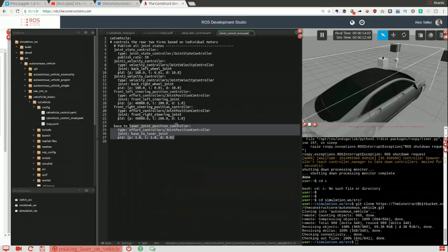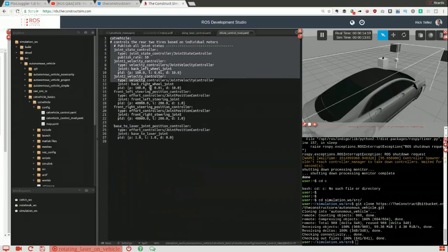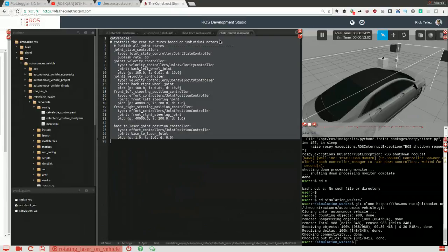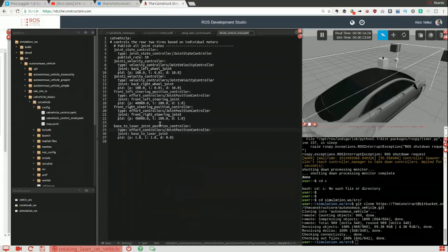Then, now, what happens? Once we have included this into the YAML file of the vehicle, we also have to specify into the launch file that launches this simulation that it has to load this controller, because this is a list of possible ones that are available for the simulation. But we have to specify, when we load the joint state publisher in the launch file, which controller we have to use from the ones of the YAML file. So we are going to do this.